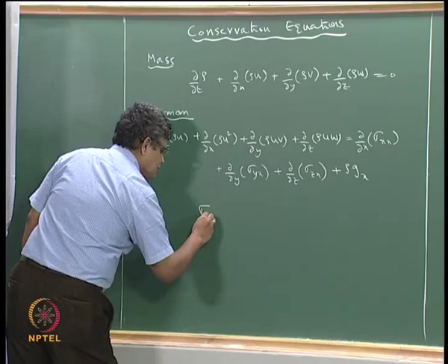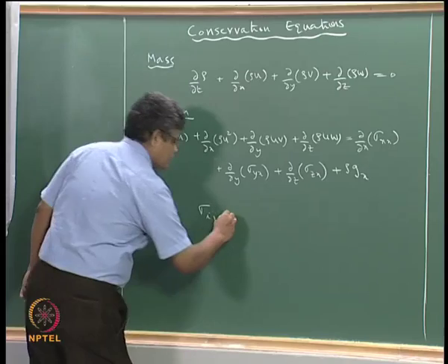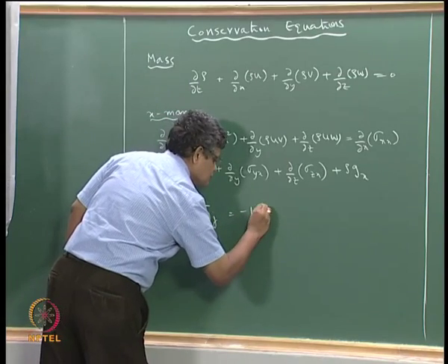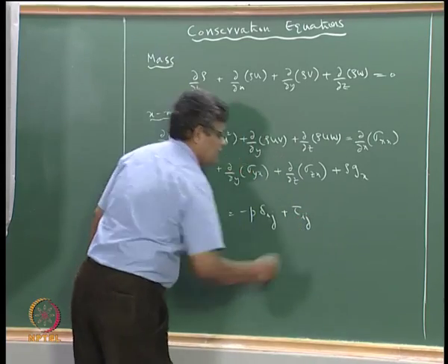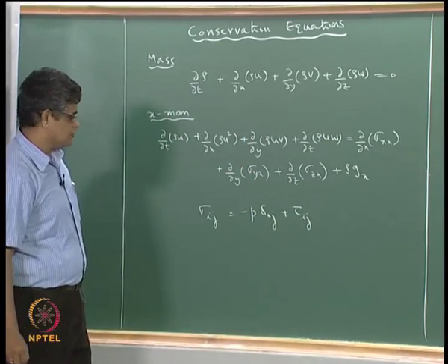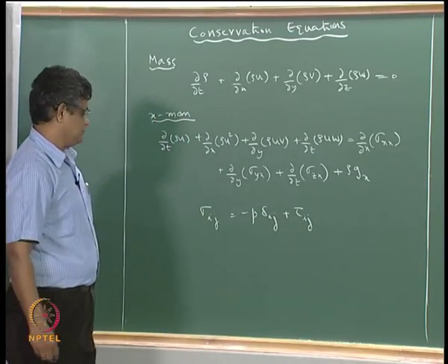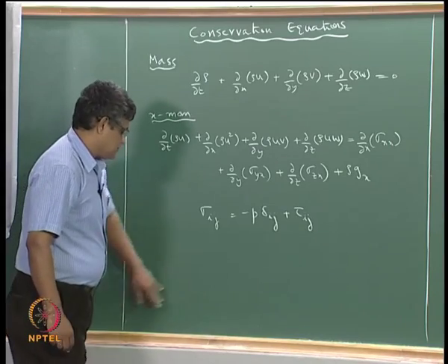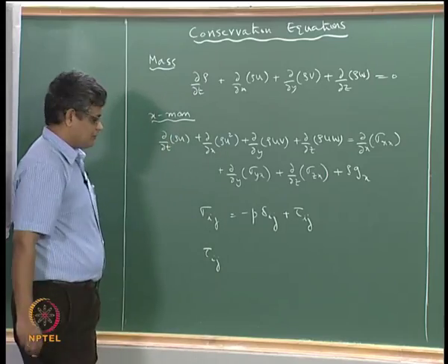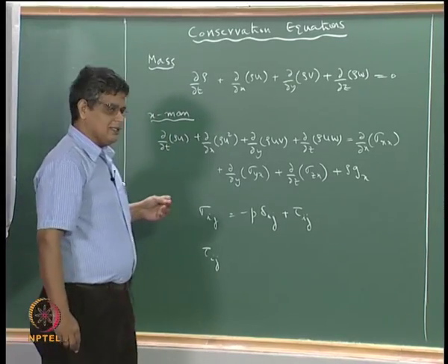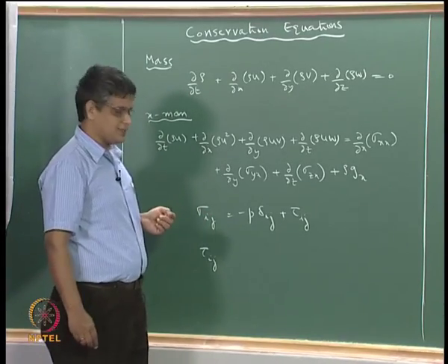We first of all divided the stress into a hydrostatic component plus a viscous stress component, which arises only from relative motion of fluid, and we said that the stress arising out of relative motion arises only from shear deformation and extensional deformation, but not from rotational strain rate.